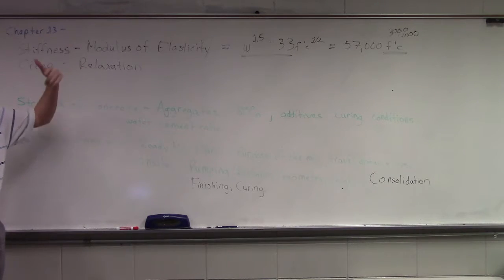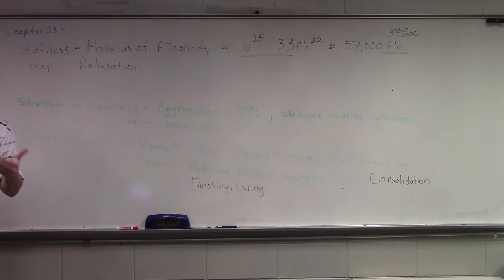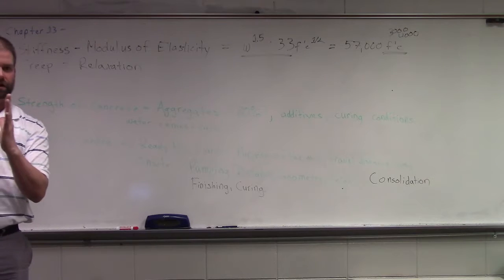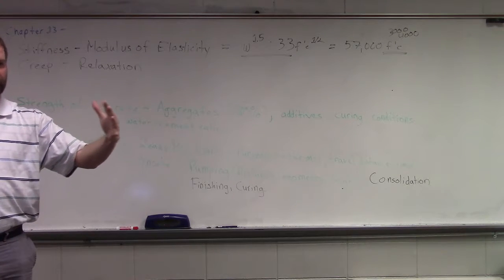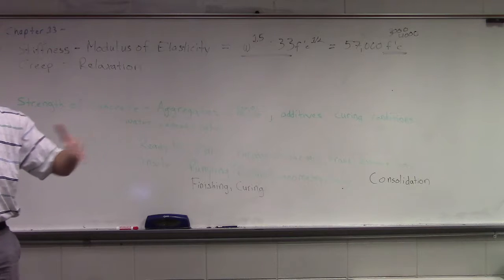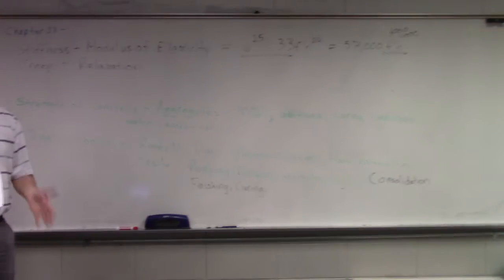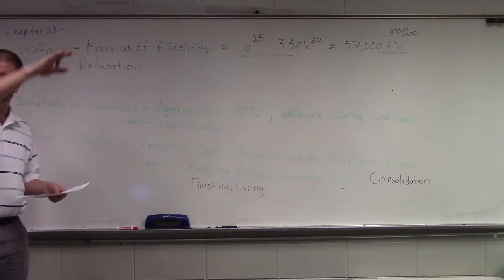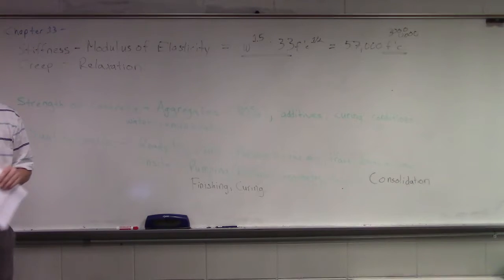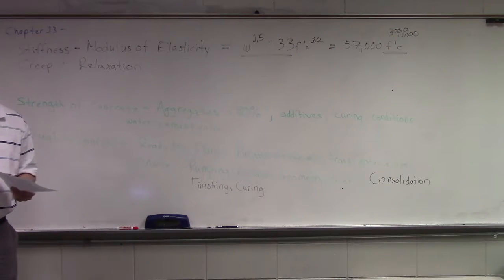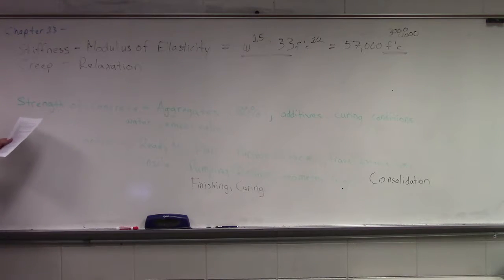What's going to happen? Think about the St. Croix crossing, the Stillwater Bridge. If we don't know what that coefficient of creep is, and we aren't monitoring it and determining it for that mix ahead of time, what could happen to that bridge? Keeping in mind that it's a bunch of segmented boxes cemented together. If it starts creeping excessively, it'll get all deformed. If you've seen the project, it's curving, it's changing elevation. We'd have all sorts of issues. We could have joint failures. We could end up with a box section falling into the river, pushing out into the landmass, etc. People would not be very happy with it.